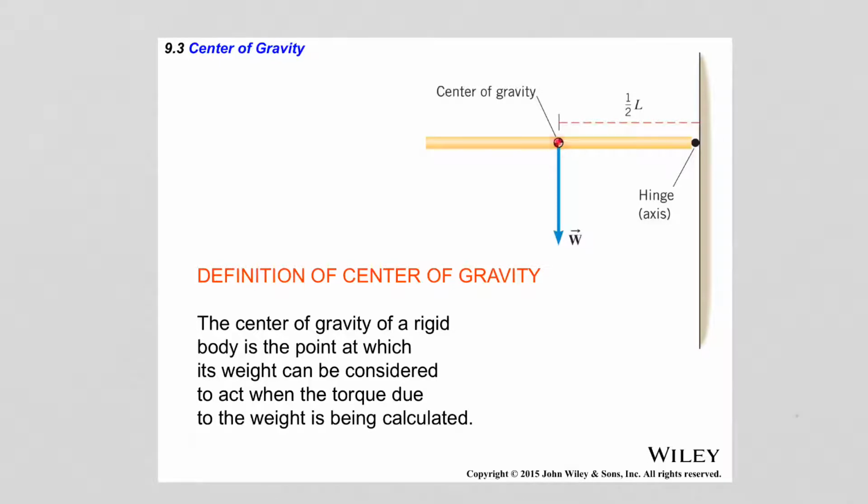The center of mass is right midway between the two ends, so that is also where the weight of this board is focused, and therefore the torque of the weight is considered with respect to that point. So the torque arm is just half of the length of this board.